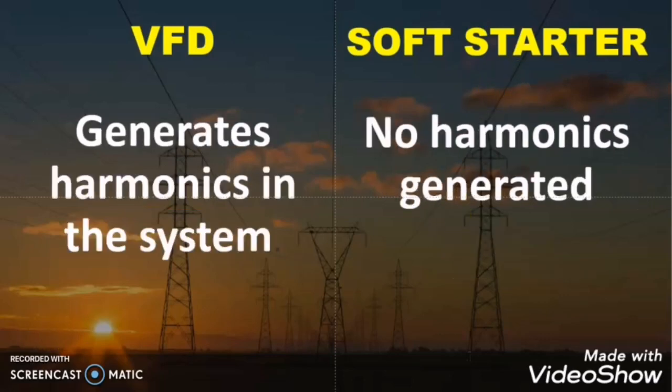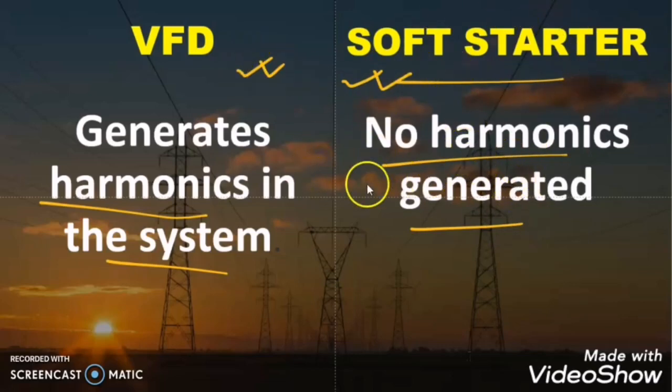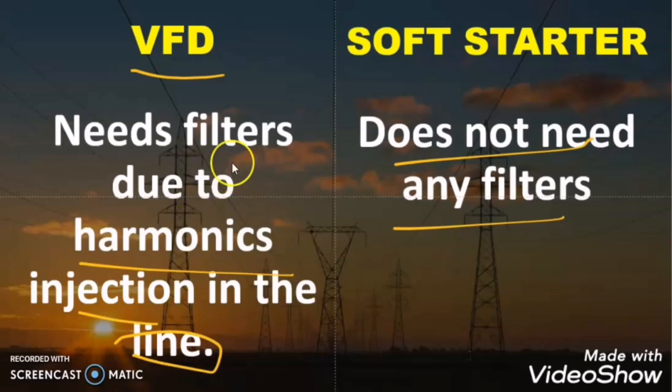The other difference between the VFD and soft starter is that VFD is generating harmonics in the system, but the soft starter is not generating any harmonics. This is the major difference, and this makes the soft starter better than the VFD. This is the first time we are finding the soft starter is better than the VFD. The second thing, as there are no harmonics, the soft starter does not require any filter to filter the harmonics, but VFD requires one, as it is generating and injecting harmonics in the line power supply. So this is the second difference where the soft starter is comparatively better than the VFD.